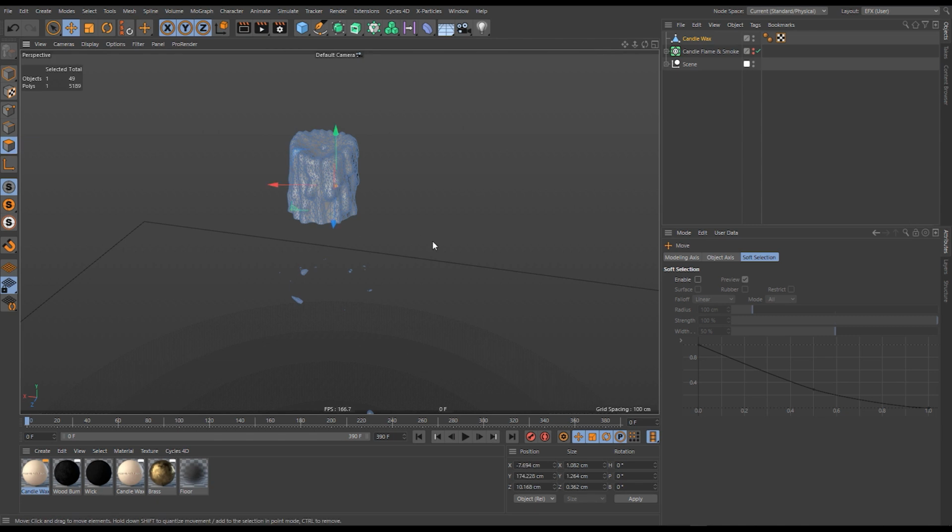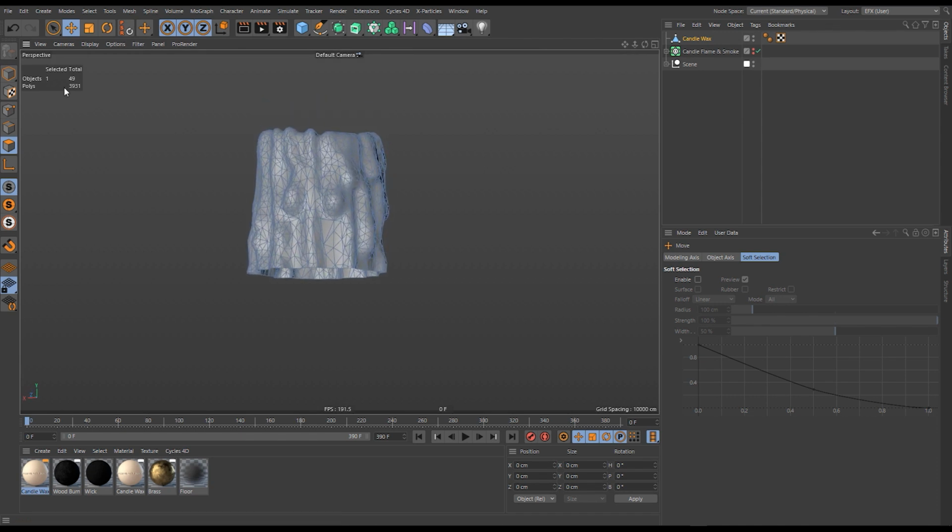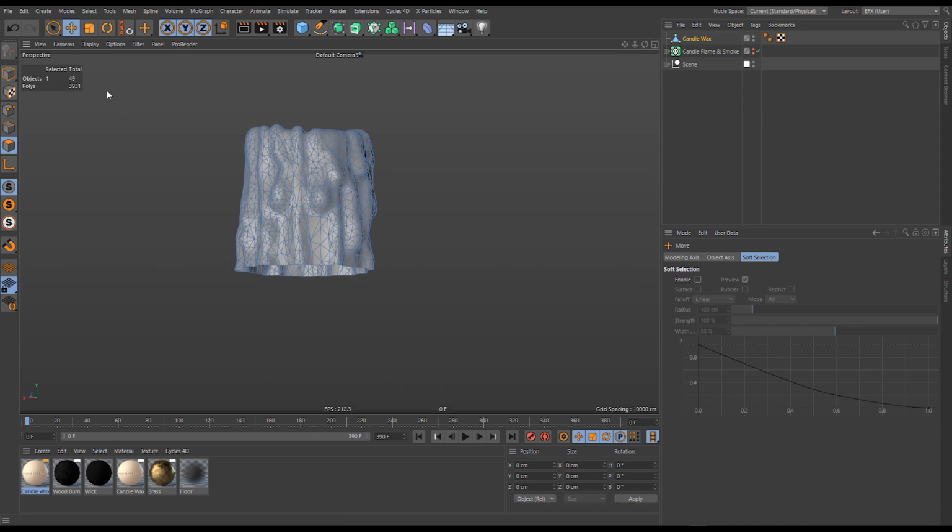And what we could do is select that one poly, or we could just double click and it'll select all the connected polygons. And then we just run the command U and then I. It inverts the selection, backspace, which clears the islands that we don't want. Okay, so we've reduced the polygon count really significantly. We're now down to 3,900 instead of 39,000.